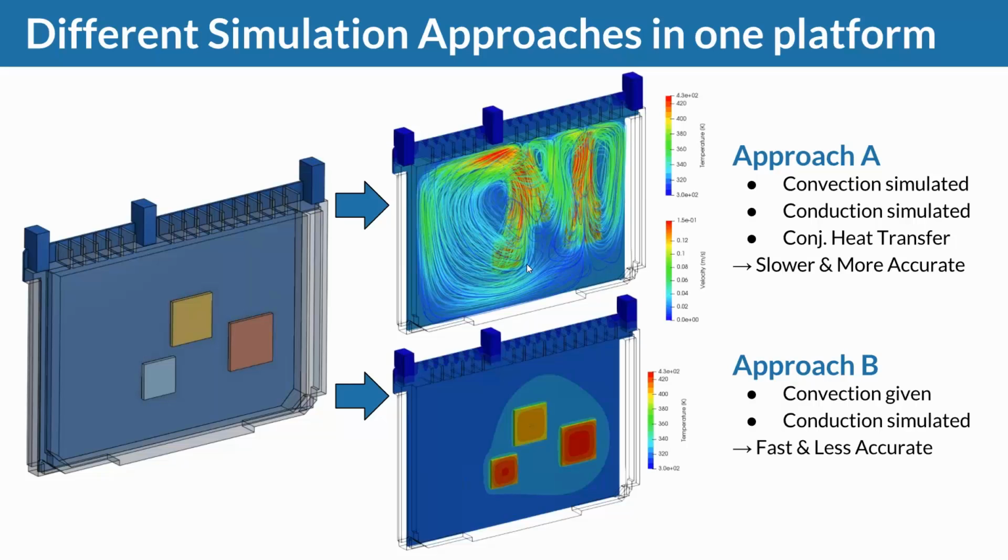So the short answer is no. But the longer answer is we're not accurately computing it, right? We're not simulating the velocity field and turbulence that arises in front of the chip, and how the air moves exactly when it cools down, how it moves back, etc. So in approach B, we didn't neglect natural convection, but we didn't compute it. We simply constrained the system or the problem with it.